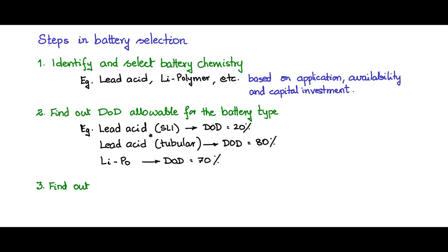Next, find out what is the watt hour requirement of the load. We need to know what the watt hour of the load is in order to decide on the capacity of the battery.